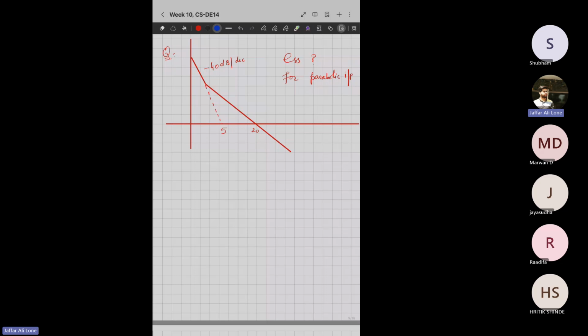Then what is the magnitude formula? Just make use of this point. Everybody please solve it, and I want answers. So put omega equal to 5 and magnitude is 0, because at 5 my magnitude is 0, and initially it's a pole, so the sign will be minus. It will be minus 20. Minus 20, it's a type 2 system. R will be 2. Minus 20 into 2 log of 5 plus log 20 log k is equal to 0. And then solve and tell me what is the answer.